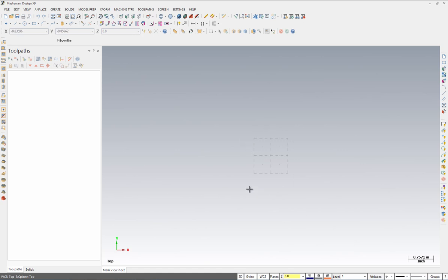As you can see here, I've gone ahead and established my grid under grid settings and changed my default wireframe color to a dark blue. I did this by going through step number 1, which is setting up the graphic user interface. I'm going to continue on with step number 2, which is to create the revolved surface wireframe.